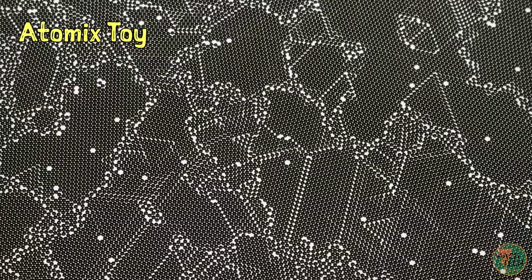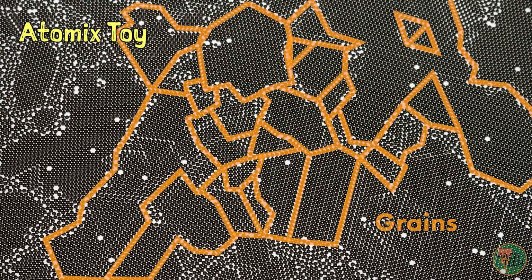However, if I use a backlight, you'll see clearly that not all the balls are aligned to one another. There are some conspicuous holes, which are like the vacancies in a crystal, but more importantly, there are large groupings of balls that are neatly packed in next to each other, but each grouping is slightly rotated relative to the adjacent ones. So instead of one consistent pattern throughout the whole crystal, there are many individual grains with noticeable boundaries where they meet. Pretty cool, right?